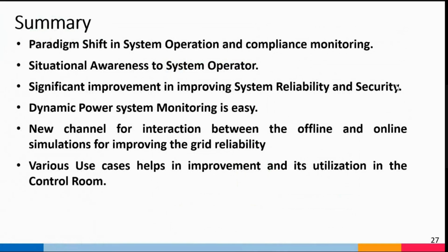So overall, the summary is that the synchrophasor, with its high resolution data, has provided a paradigm shift in the operational activity as well as the compliance monitoring, which is very important for grid operation, basically to see whether all the equipment is in compliance with the proper standards or not. Because most of the compliance is during the dynamic state, you need to focus on whatever is already inbuilt in the system. It should respond properly so that your stability is improved during the fault or any event, because at that time the operator cannot directly do anything, as these are happening in milliseconds. So at that time you rely on the automations, basically whatever automated actions are there.